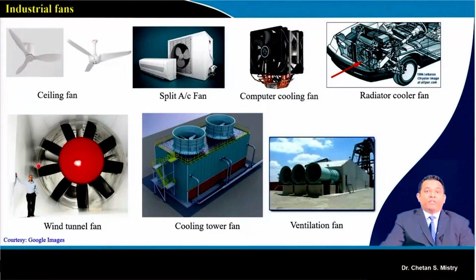Say, this is a wind tunnel fan. Wind tunnels, as we have discussed, are used for aerodynamic testing of different components. They have a wide variety of applications, including aerospace and building construction. They are used for flow field study, detailed flow field study. So if you look at this tunnel, based on my test section, the size of the fan varies, and this fan is mainly used to overcome the friction losses that happen in the duct.